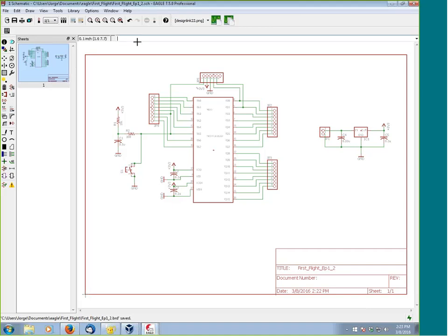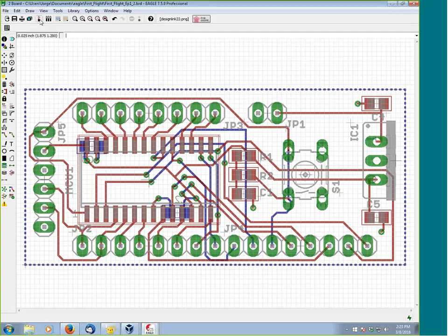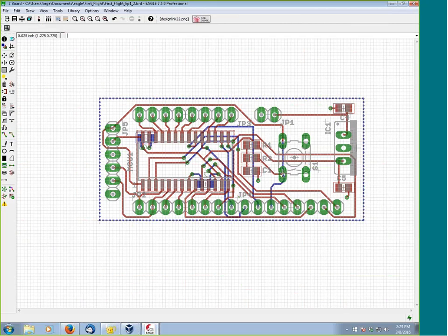So let's go on to the next thing we can produce. Okay, the rest of the manufacturing data all has to do with the board. So we're here in the board editor. Now normally when we're talking about manufacturing data for a board, usually we're talking about generating the Gerbers. However, there are occasions where other files may be requested of you. So we want to go ahead and take advantage of this time to cover the various things they could ask you for. Okay?